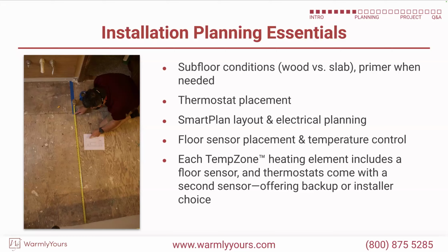We also include the floor sensor placement on that plan, so that's important to know for your temperature control. And also, we want you to know that the floor sensor now comes complimentary, included with your heat mat or cable. So you get one sensor in your box with your thermostat, and you get a backup sensor included with your heat mat or cable. So you install them both, run them up to the thermostat, but only attach one and leave the other sensor balled up in the back of the box. In case that other one ever goes bad, you can take it off and put the other one in, and you are golden. So it's very, very important to get us the dimensions.